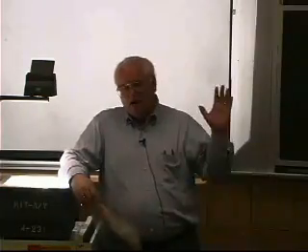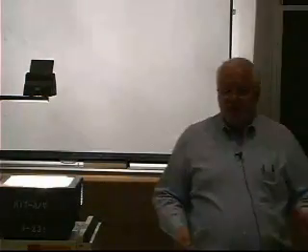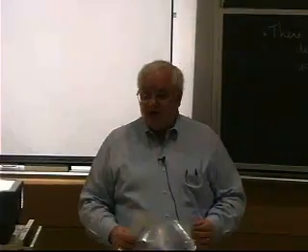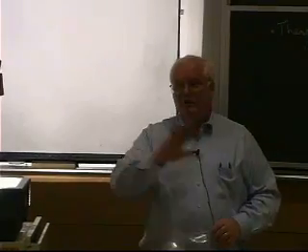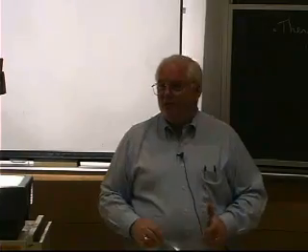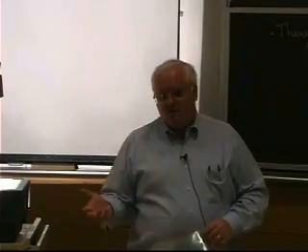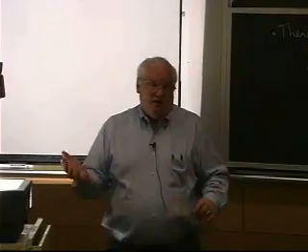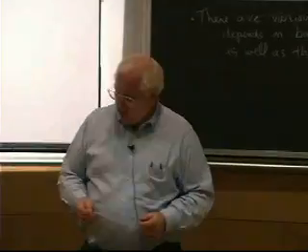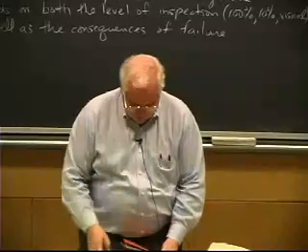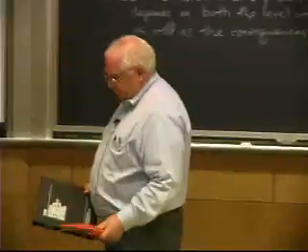I quite often say, well, let's do an X-ray. Because then we don't have to get permission from everybody because we're doing something destructive. We just go out and do it. And sometimes you learn enough from the X-rays that you don't even need to do anything else. There have been times I said, I don't want to do anything else. I can see everything I need to see on the failure on the X-ray. That's like 10% of the time you get that kind of very positive result. Sometimes you see nothing on the X-ray. In fact, I thought about bringing some X-rays up to show you of an aircraft failure where we know it's the part that failed, but we didn't see anything on the X-rays that really was very exciting.